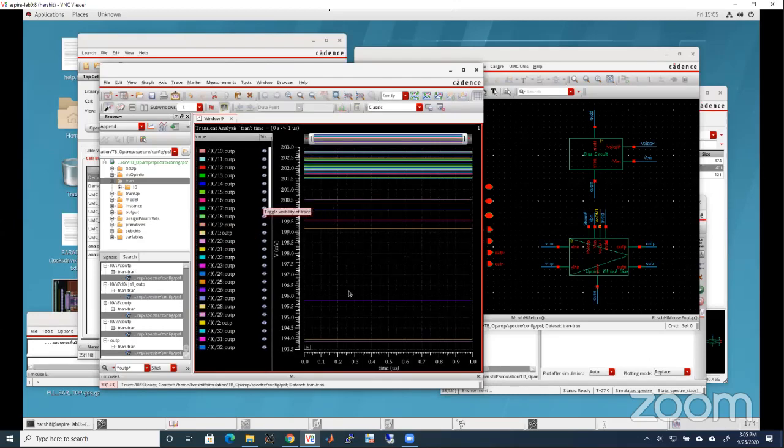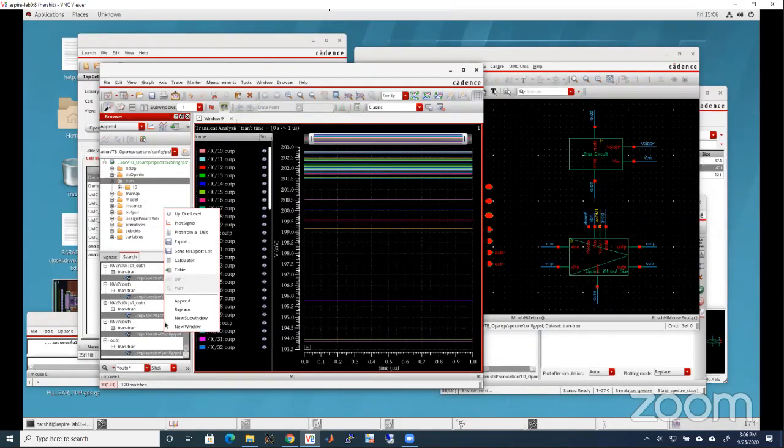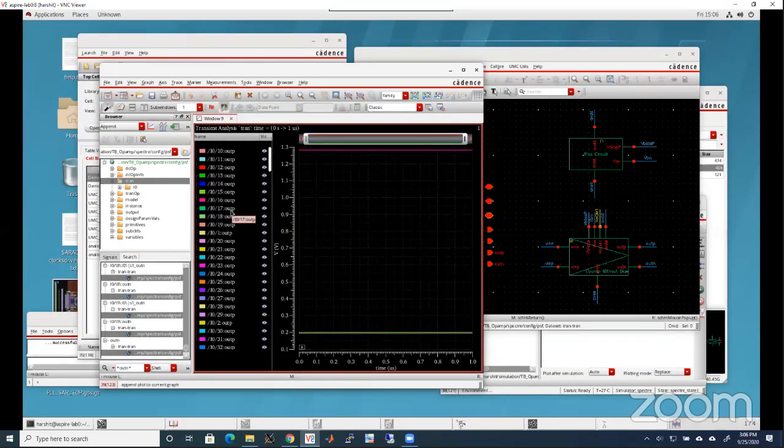So you can see that, oh, probably some bias voltage somewhere I messed up. So some voltage is not properly set. So that's why we are getting this 200 millivolts, but that's okay. So now I look into out N. Okay. And I will plot all the out Ns and remove the stage 1 output N. So now I have to remove all the stage 1 output N.